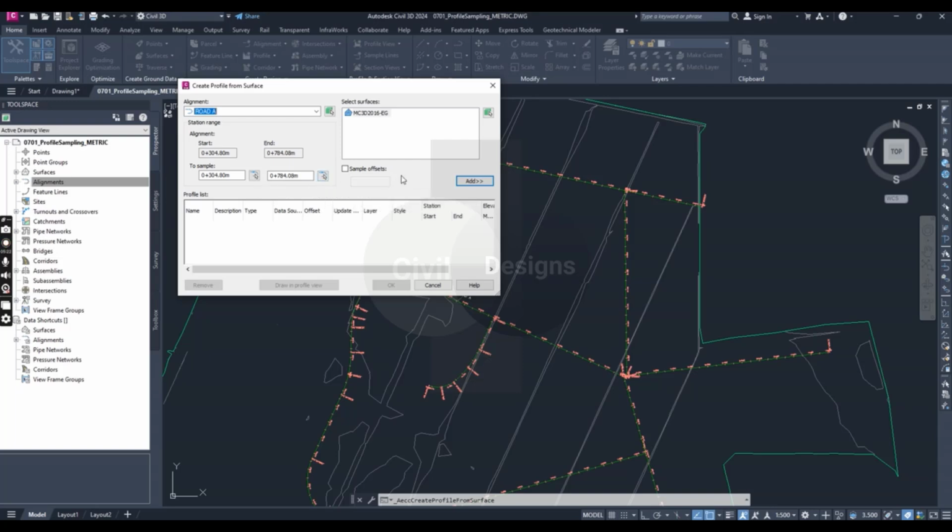The second thing, the upper right corner, is where we specify the surface that will be sampled, and it allows you to add sample offsets here. We can select a surface from the list, or click the pick on screen button. Beneath the select surface boxes is sample offsets.